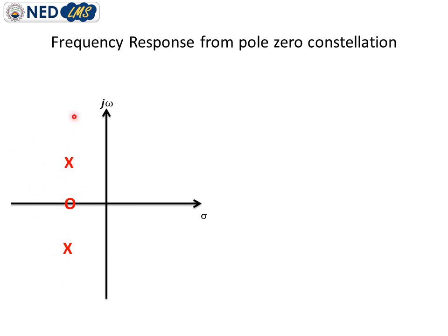There are two poles in the system which are on the left hand side of the S-plane, and as I already stated that this zero or any zero will not contribute to the stability of the system, so we will not see the position of zero. Zero can be on the positive x-axis or maybe on the negative x-axis.